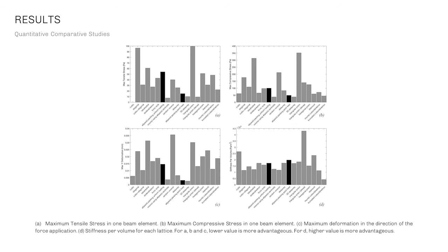However, there are limitations for this result. We chose the piping radius of 2 mm based on the expected dimensions of our physical prototypes. But each individual lattice does have an optimal piping diameter to maximize the performance. Hence, we may not have chosen the ideal radius for the ellipsoid packing algorithm to demonstrate its full potential, or we may have chosen a radius that causes other lattices to perform poorly. So the current results should only be considered on the scale of those prototypes. If we want to change the scale or extrapolate the results, more testing would be needed to explore the dependence between the performance and piping radius.